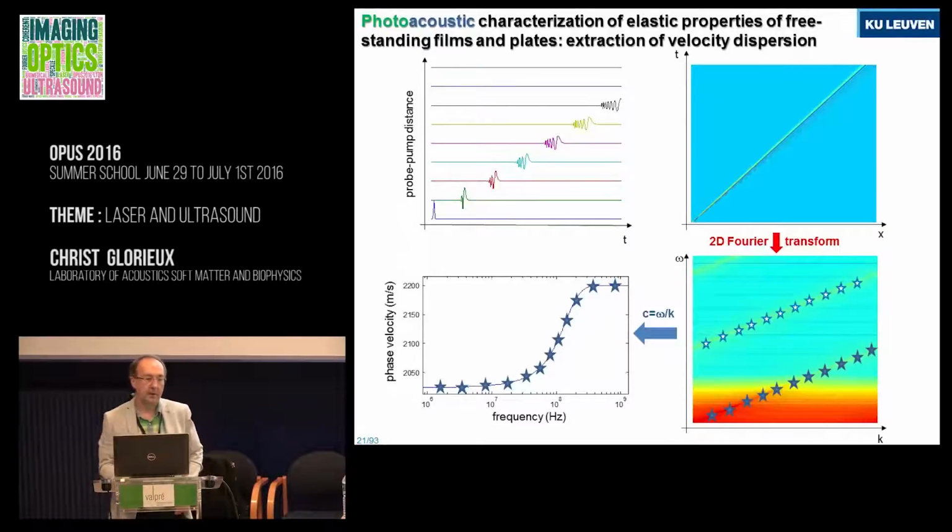How to measure? To measure, we excite waves at one position. This is excitation of a pulse in time and also in space. In space, we have a thin Gaussian profile. Typically, we use laser lines to excite the waves, and that's what you see here in the bottom left. It's a bit small, but you have a Gaussian wave. When you look at the displacement of the sample very close to the source, the wave is Gaussian.